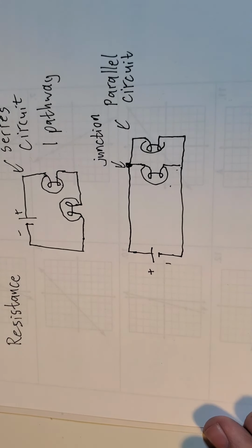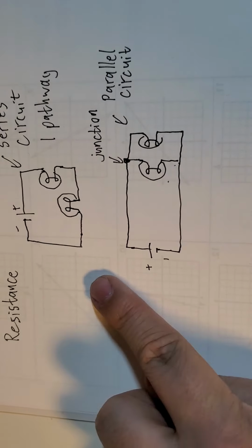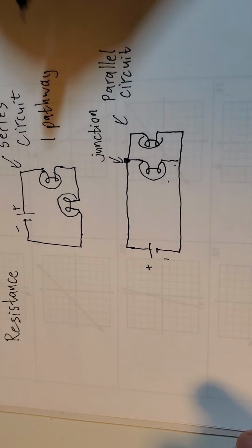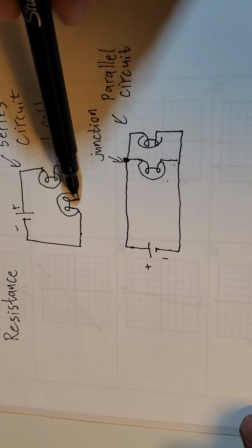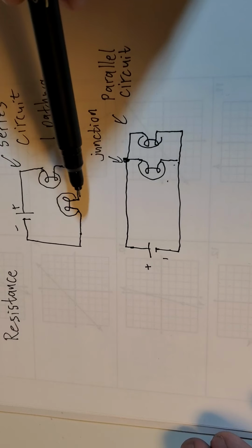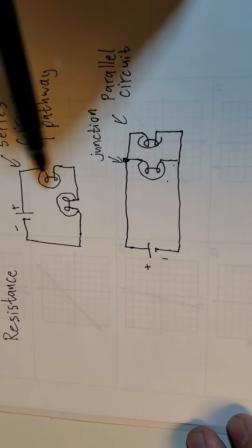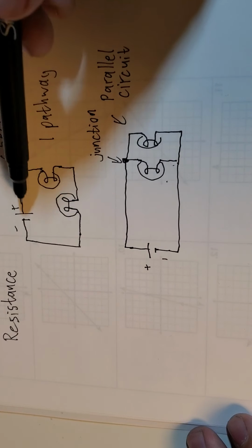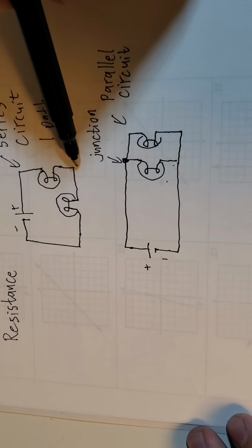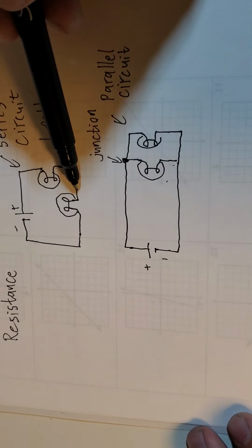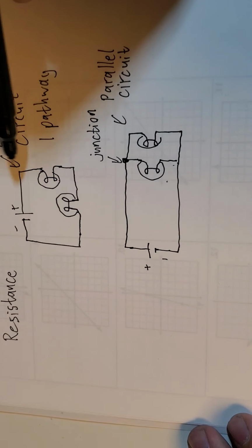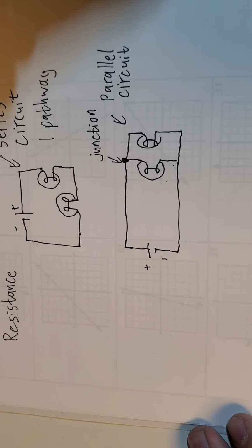Now again, this is a parallel circuit, this is a series circuit. One of the interesting things though is, for example, if this light bulb here in the series circuit burns out, right? I'm not actually going to cross it out, but say it burns out. Well, now you don't have a complete loop. You would see that we would go here, we would go here, and then it would stop because this is burnt out. So your entire circuit won't work in series if one thing breaks down.